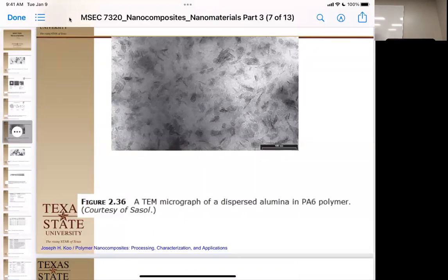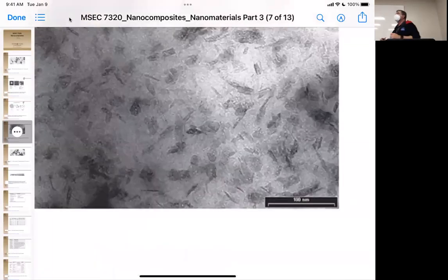So it started with a macroscopic powder that went into the extruder, and then as it got through the shear, the polymer was in between the different particles as they mechanically sheared. They didn't have the opportunity to recoalesce because the polymer then got to that dispersion. But again, notice the irregular shape of these crystallites. Okay, so we don't have spheres. We don't have long aspect tubes. We don't have plates. We have these really rugged, sharp crystalline regimes. And that's going to change our properties.